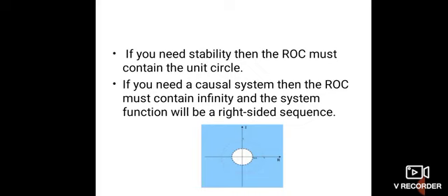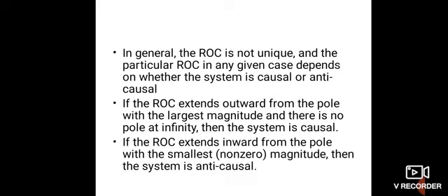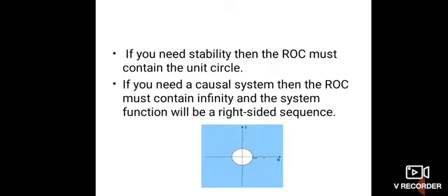If you need a causal system, then the ROC must contain infinity and the system function will be a right-sided sequence.